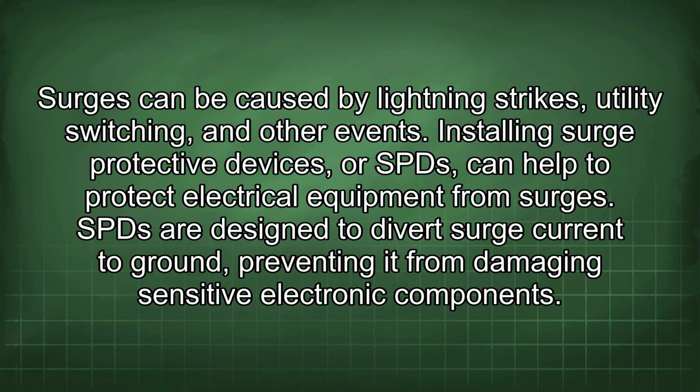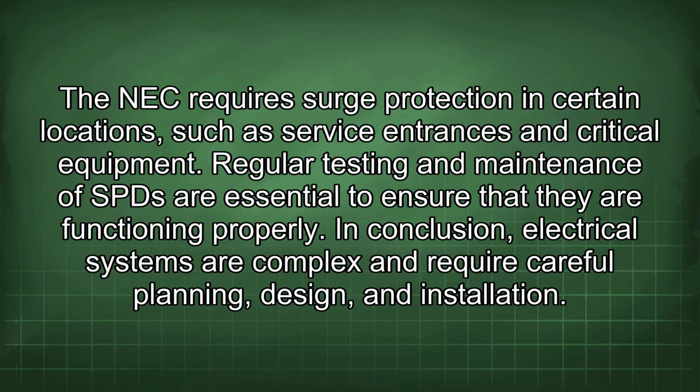SPDs are designed to divert surge current to ground, preventing it from damaging sensitive electronic components. The NEC requires surge protection in certain locations, such as service entrances and critical equipment. Regular testing and maintenance of SPDs are essential to ensure that they are functioning properly.